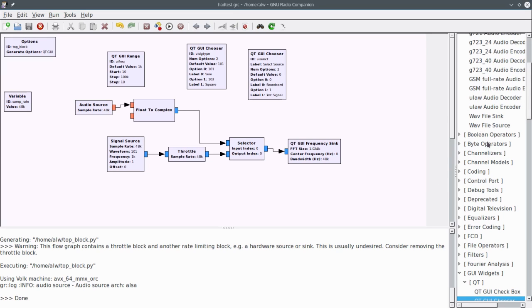It's pretty simple to get that kind of stuff set up, and it's really easy. If you need something really complicated, you can either write your own blocks in Python. There's a way to get into C and C++ with that as well, or you can just write code. And none of this is something that couldn't be done without using GNU Radio Companion. It's just so easy to make these flows up and get everything working instead of having to tie all this together in code. Just the same kind of way you might build a GUI with a GUI editor instead of writing a bunch of code to create widgets and size windows and all that sort of thing.